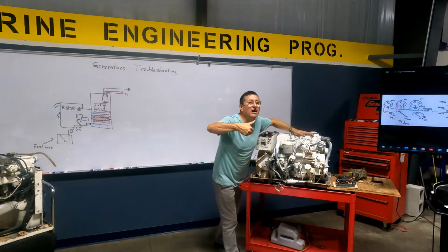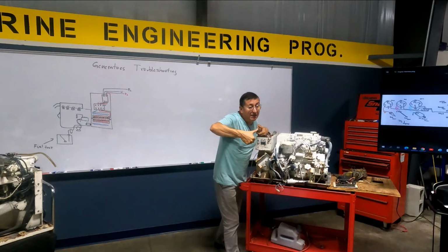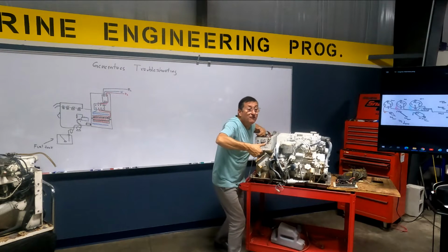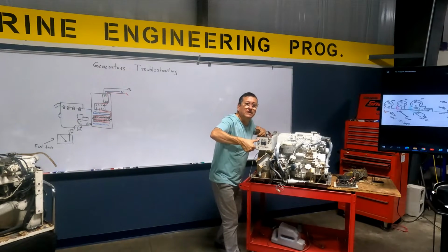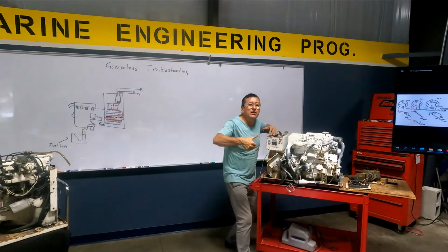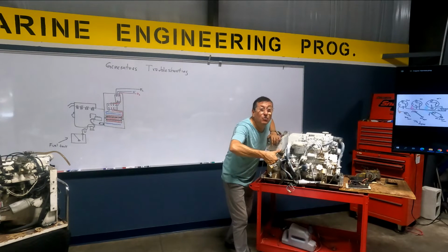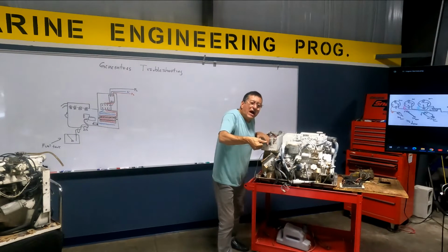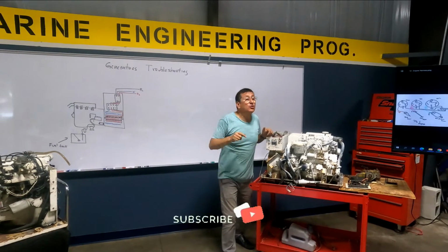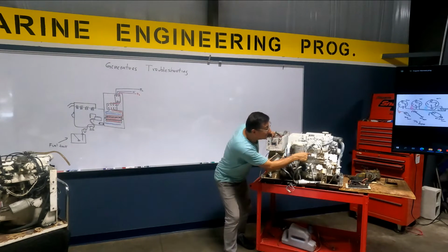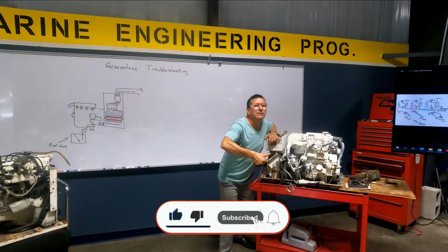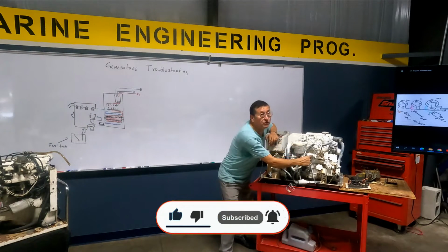You remember when you have the preheat button pressed, and you continue with that button pressed for 10 seconds until what? Because if you remove your finger from the preheat button, the engine stops. What happens if you remove your finger from preheat? You don't have power in the crank relay, you don't have power in this solenoid, the engine stops. Yes or no? You need to put your finger back, and the engine continues running because you open the solenoid again.